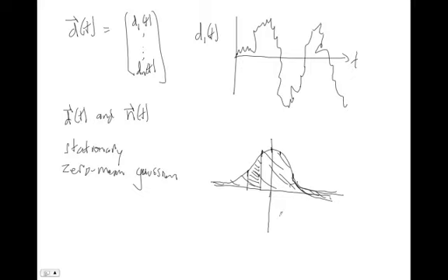And then finally, the last thing that we use to describe this noise is we say it's white noise. White noise basically means if at one sample I measure my disturbance and it's right here, at the next instant in time, even if it's a millionth of a second later, the disturbance is equally likely to be anywhere else on the distribution.